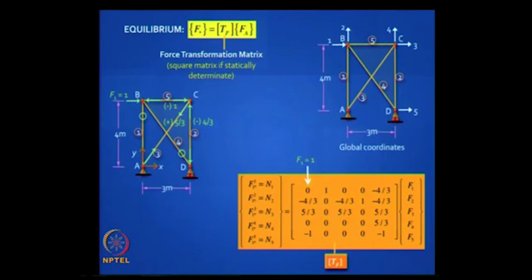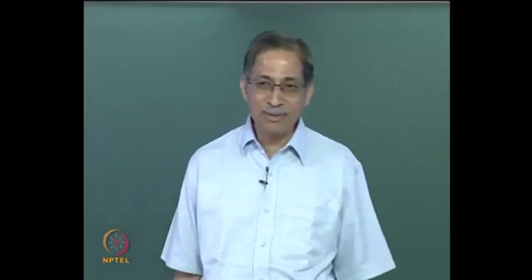TF matrix is very comfortable because we were raised on statically determinate structures, that is our fodder, so it is very easy to generate this, especially the second one, F2 equal to 1 has only one element, okay. So you understand what TF matrix is, good. Now let us take any element in that, okay, that element we used to call N31, remember small n for unit loads, N31 refers to the force in bar number 3 caused by F1 equal to 1, remember we have used this notation earlier. It is called the force transfer coefficient. Why is it called a transfer coefficient?